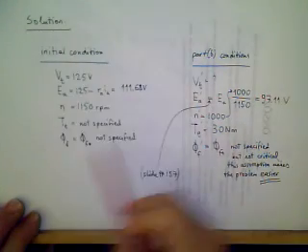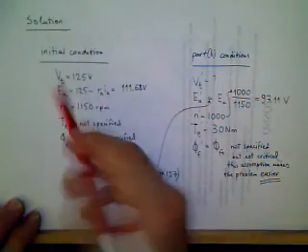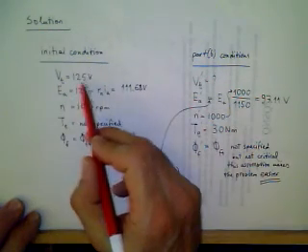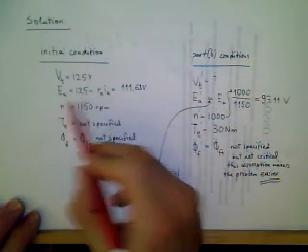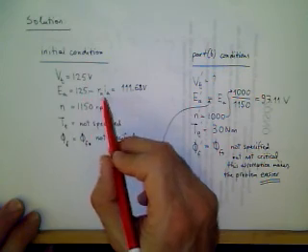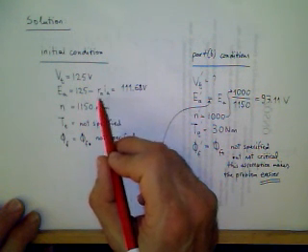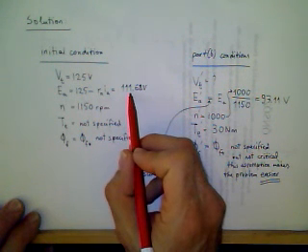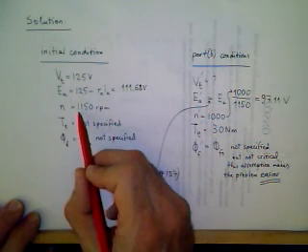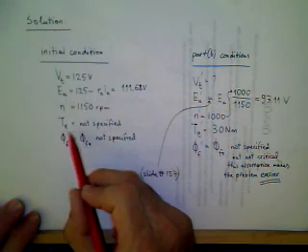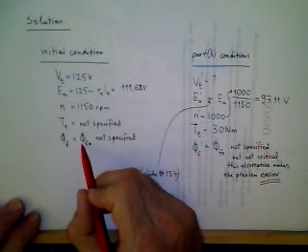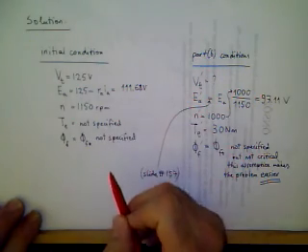So this is the set of the initial conditions. Initial condition means before the speed control. In part A, terminal voltage was 125 volts. EA is from that value we deduct the voltage drop across the armature resistance, which is 111.68 volts. Rotational speed is 1150 RPMs. Torque is not specified in the first part, and field flux again not specified.